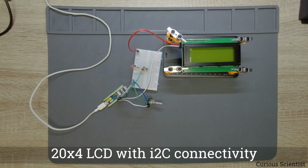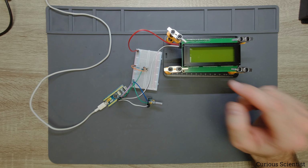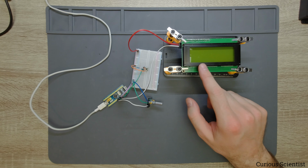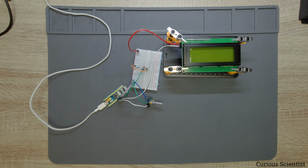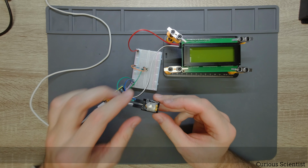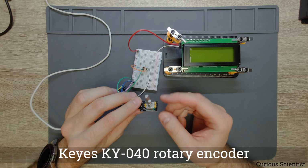This display is a large 20 by 4 LCD with an I2C connection, so we just need 2 wires, and the 20 by 4 means that we have 4 lines and each line has 20 blocks, so we can print 20 characters in each line. So that's very nice.